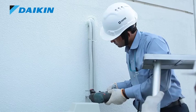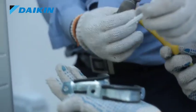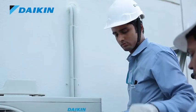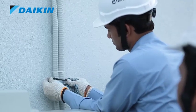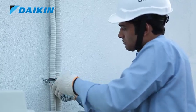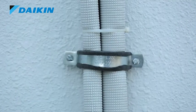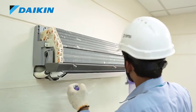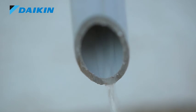Once the drain pipe is positioned properly, clamp it properly with the wall. After fixing the drain pipe, pour water and ensure a free flow of the water. Check physically that the drain water reaches the outlet.